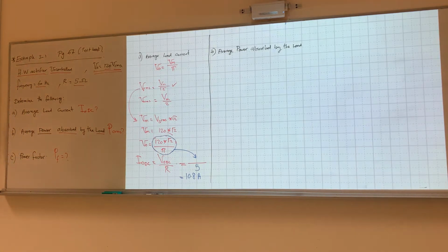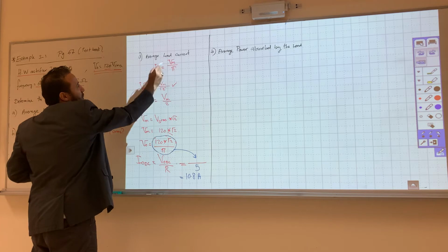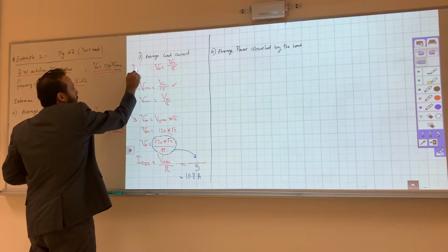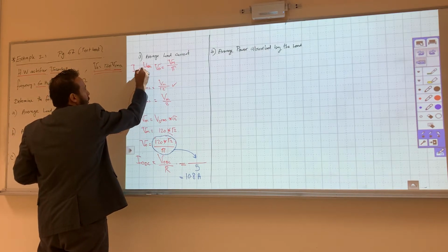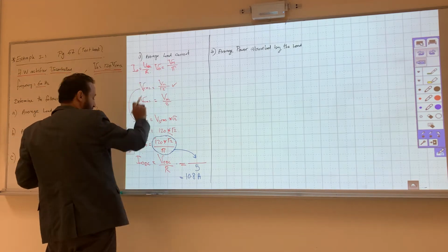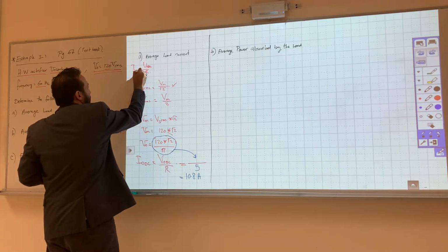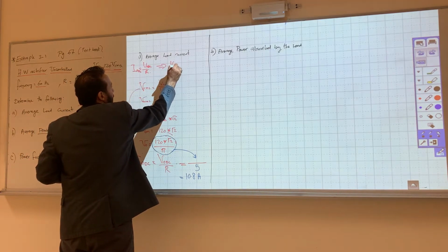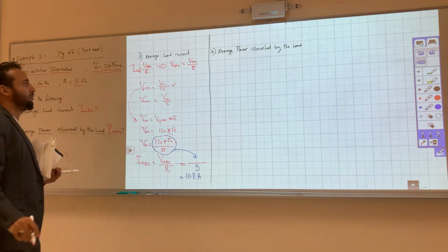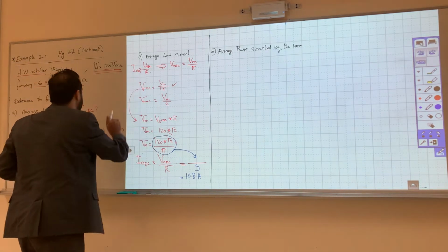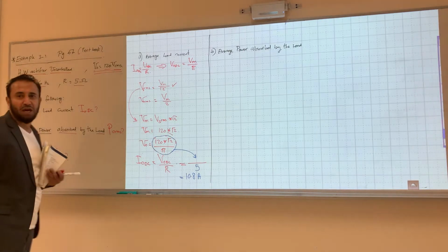Even before here, I started wrong. It should be, they're looking for the average load current, which is I out DC equals V out DC over resistance, and the V out DC equals the V max over pi. And then we go from there. But this is what they're looking for. I had the issue here and I carried it with me there. Anyway, now they're looking in part B for P out RMS.